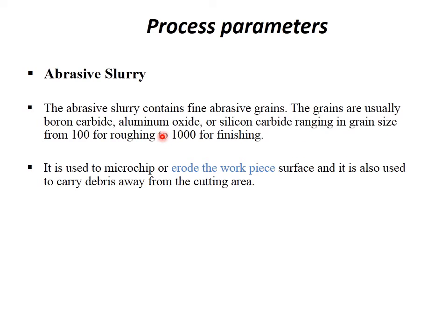Not only the type of abrasives, but also the size of the abrasives, or grain size, matters: whether to use a coarse grain size or fine grain size. Again, it depends on the type of workpiece material you want to cut. If you are using a larger, coarse grain size, then you may have better MRR, but at the same time you may not have a proper surface finish.